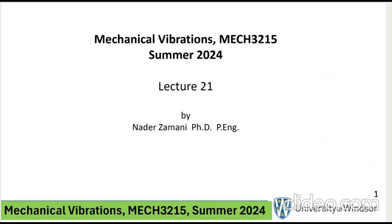So in the lecture today, we want to be able to include the damping, and we're going to do that 2 ways. One of them is called modal damping, and the other one is Rayleigh damping or proportional damping. And towards the end, we talked about the issue of resonance, which is to some extent similar to what we did for a single degree of freedom system, but there's a caveat. You have to be careful because it is possible that the driving frequency matches the natural frequency, but still there is no resonance. So there is a caveat there that we're going to discuss in the last 10 minutes of the presentation.